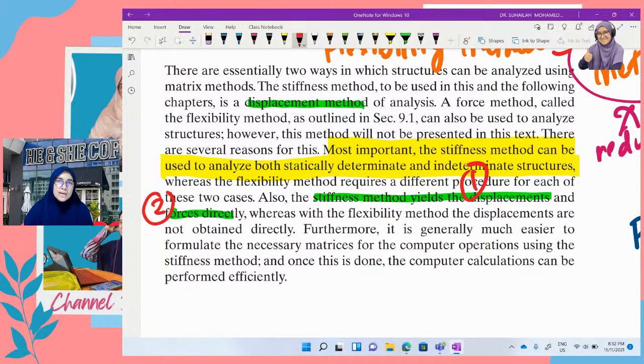If we want to calculate displacement at C, we have to apply a unit value at C in order to calculate displacement at C. So we have three sets of solution in order to calculate the displacement. That is not flexibility method. In order to get displacement, we have to extend the analysis. We apply another method, which is actually the unit load method, to calculate the displacement.